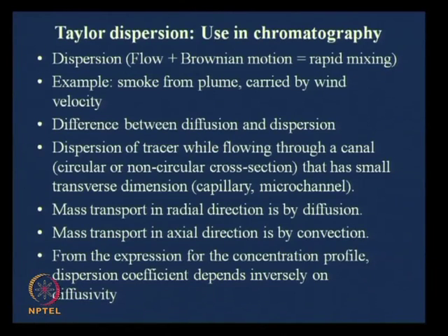Now this Taylor dispersion is important when you have a small transverse dimension, that means either a capillary or a micro channel. Now, what you take into account while defining the governing equation is that mass transport in the radial direction is by diffusion, and mass transport in the axial direction is by convection, because in the axial direction there is a flow.